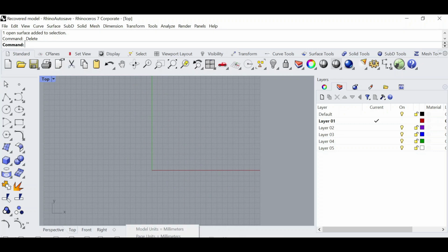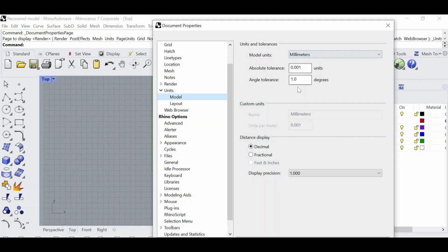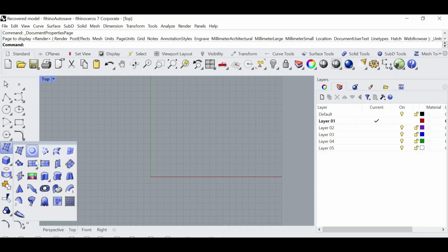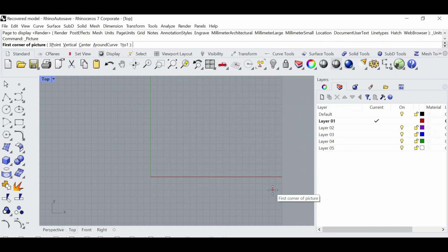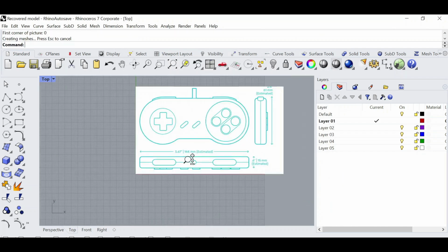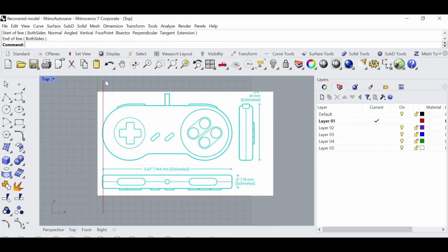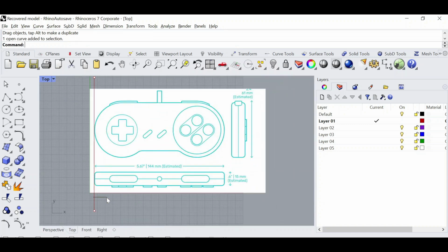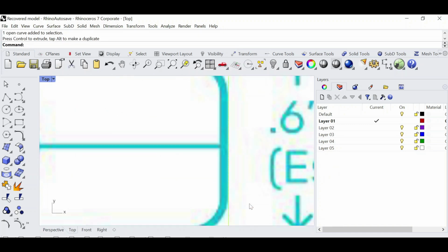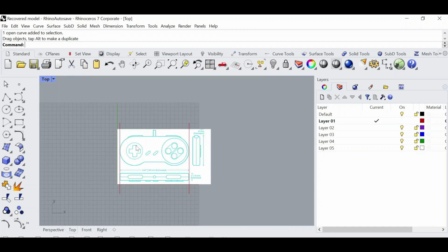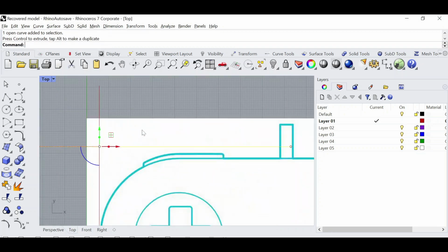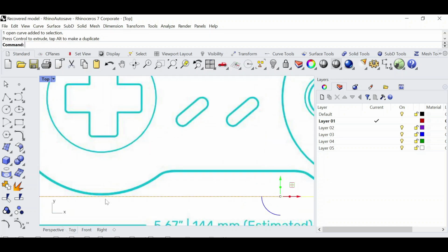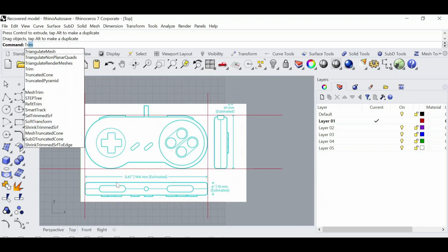in Rhino. As always, after setting the unit and grid structure of our workspace, the first thing we need to do is to scale our image to the approximate actual dimensions of our product, with the scale command at the appropriate scale according to our reference image. Because if we do not do this, we will not have a drawing close to the actual production dimensions of our product. After downloading our reference image, let's put it on our stage with the picture frame command with the 1:2 option and scale it with an appropriate scale command. Let's not forget to set auxiliary reference lines and points for this, and then we can start our reference drawings.